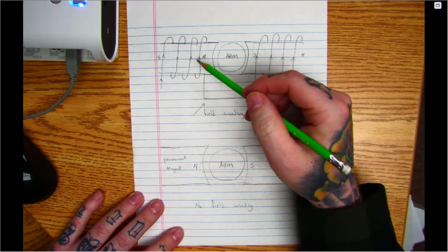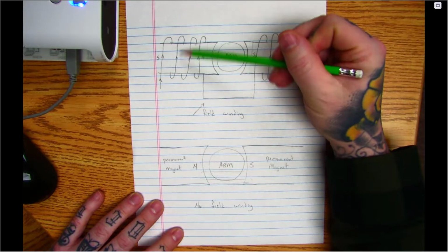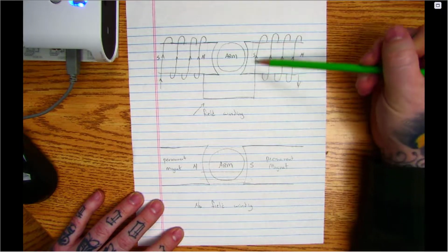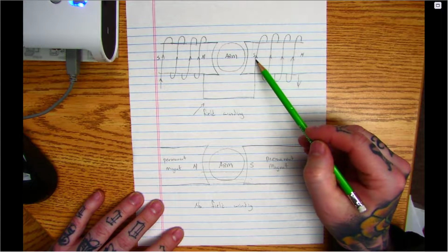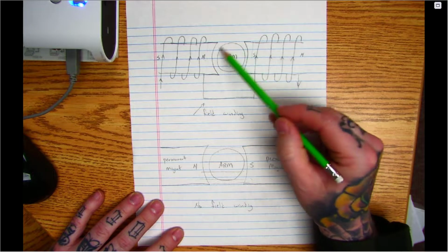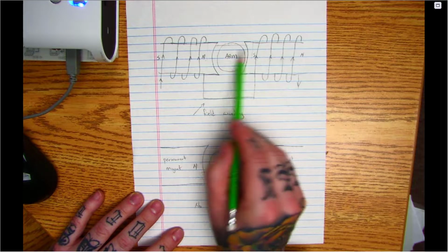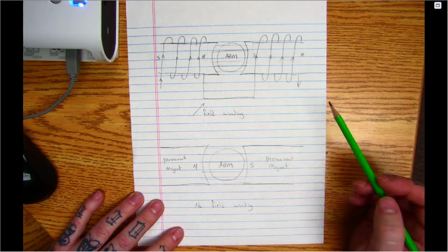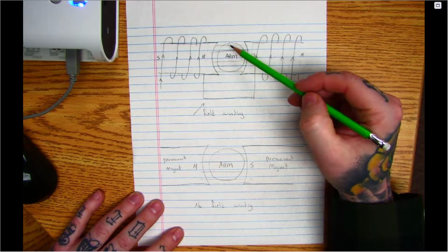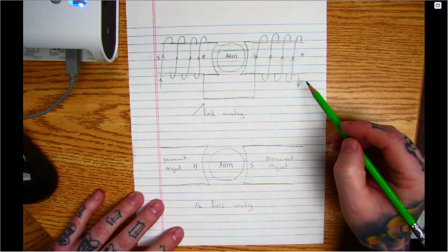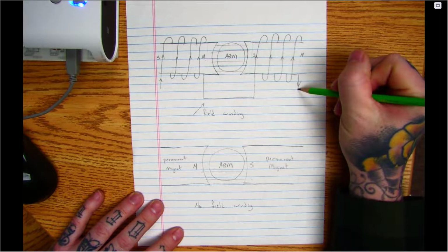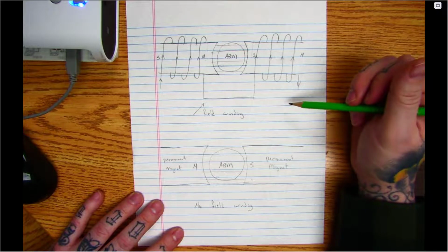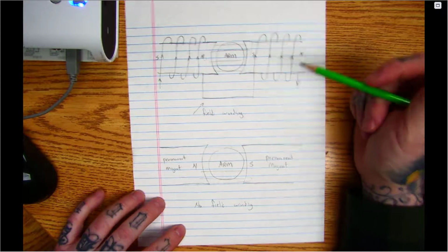This is the scenario where we have current flowing through these windings onto the other side, which creates a north and a south pole, so that when this armature spins through here, again, we do have magnetic lines of flux, but we can adjust the intensity of these magnetic lines by how much current we have going through these field windings. So you'd have a rheostat in series with this, basically controlling how much current goes through there. It's just something I usually draw out to help.